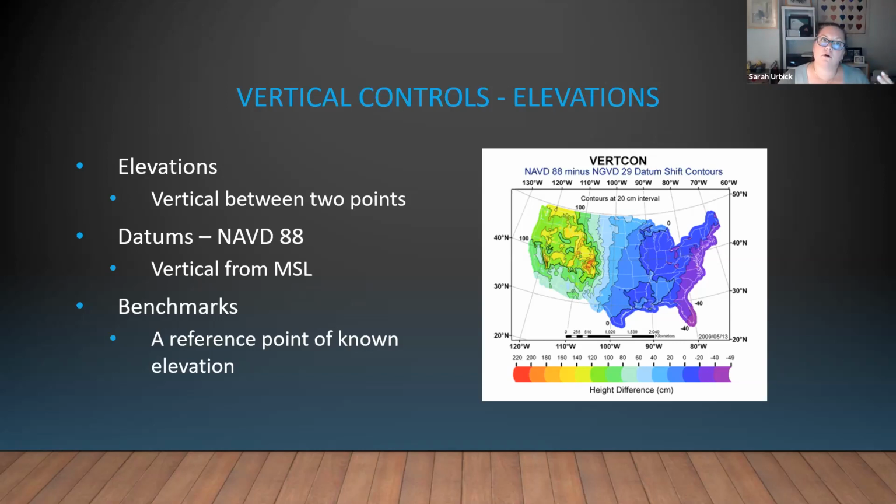So we tend to be a little bit more correct when we start talking about vertical differences. Okay, what's the distance vertically? We're not going to use something like stationing. Stationing cuts down the number of significant digits. Vertical distance, we need to get a little more precise with that end of it.